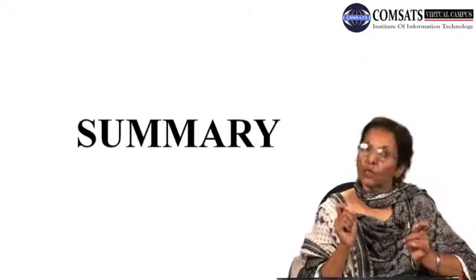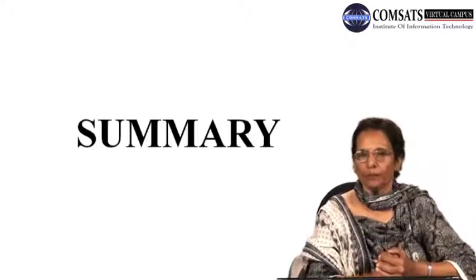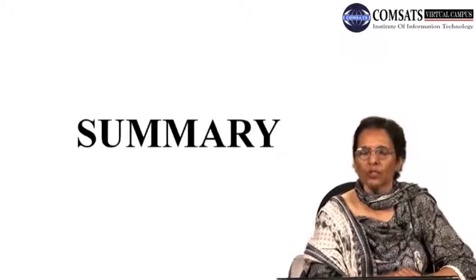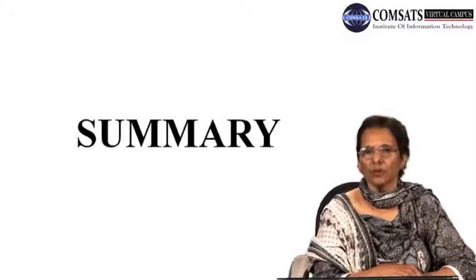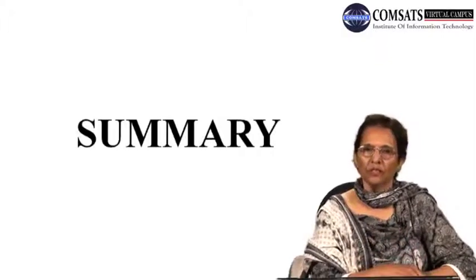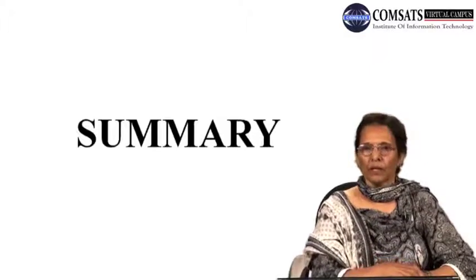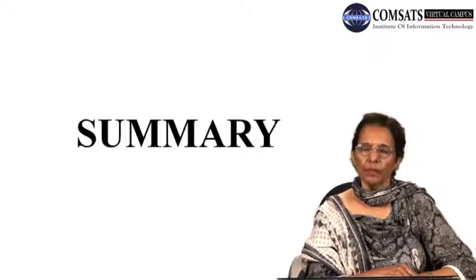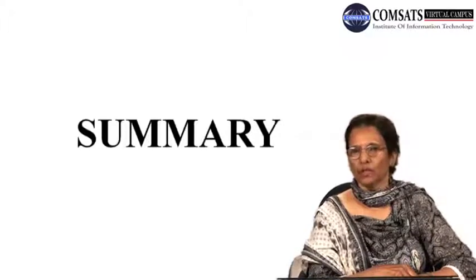कि ये constant सिर्फ एक temperature पे ये value constant है, जब आप temperature बढ़ाएंगे तो ये constant Ni भी बढ़ जाएगा. तो ये एक absolute constant नहीं है. Ni इंट्रिंसिक कैरियर कंसंट्रेशन कांस्टेंट है एक ख़ास मखसूस टेम्परेचर पर, और लिटरेचर में ये वैल्यू कोट की जाती है, दी जाती है रूम टेम्परेचर पे 300 केल्विन पे. Having defined this basic assumption that in equilibrium the carriers obey the law of mass action, that is the thermodynamic equation n dot p is equal to Ni square.